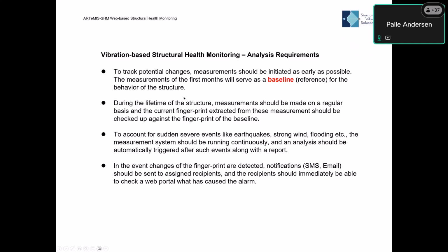And of course, it would be very desirable if you can make the measurements continuously, because that will enable you to react if there are any sudden, severe events like earthquakes happening to the structure. If you only are measuring it, let's say once per 2 years, and then compare with the baseline, then you cannot really act in between these periods if you don't have any measurements there. So it's a really good idea to have a continuous monitoring system installed on your structure.